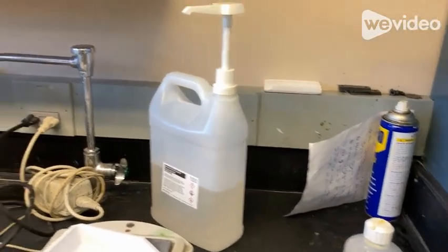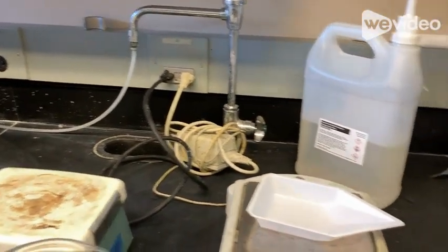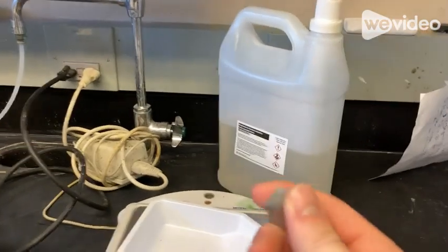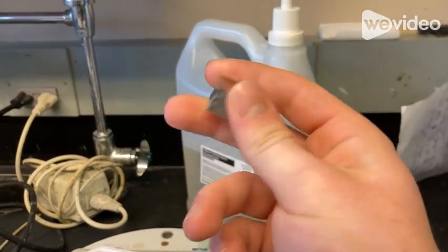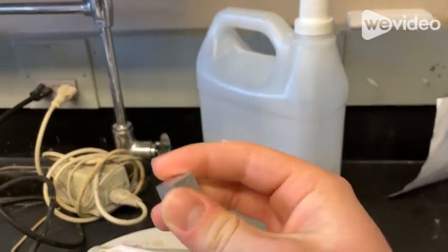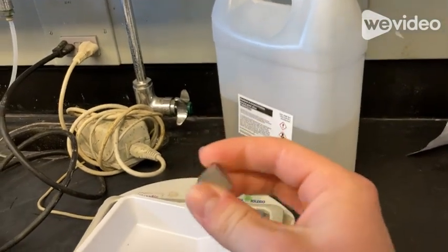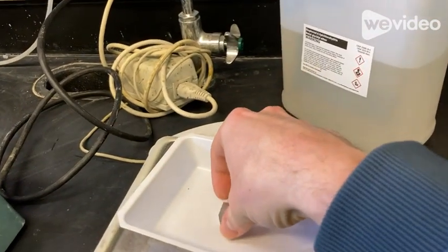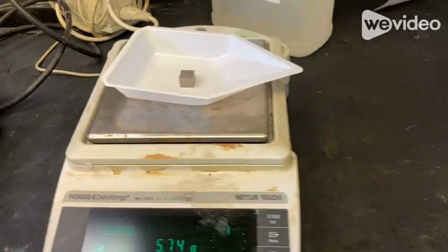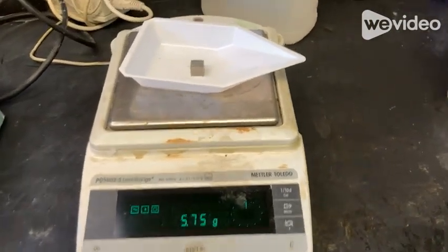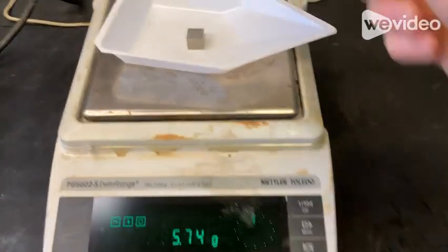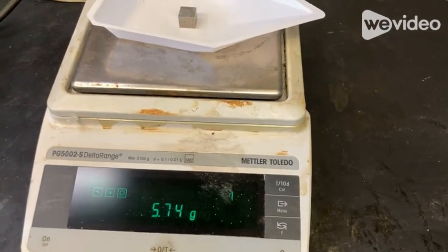So for my final project in MSE3210, I decided to deal with 7050, a high strength, high corrosion resistance aluminum alloy. You see right there, it's about a 12.5 millimeter cube. And what I'm doing right now is I'm just getting the mass of it. After that, I'm going to put it into a furnace that's at 135 Celsius and measure the time for it to hit 120. The initial temperature I measured before, it's about 17.5 Celsius.